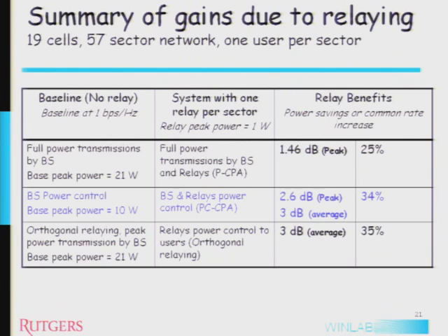So I think there are a couple of points I wanted to bring up. First, I don't have a feel for how sensitive this 2.6 or 3 dB is to the setup that you have. Did you run any experiments with different intersite distances, different models, different propagation exponents? Something like receive diversity could also make a difference in what that number is. Do you have any feel for how robust this gain is to different deployment settings and assumptions, such as receive diversity?